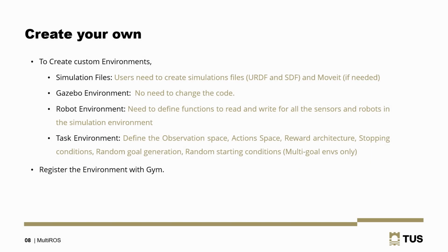To create your own environment, the initial stage is building the simulation of the task in the Gazebo simulator. So users can create a URDF file for their own robots or use the files provided by the robot manufacturers to spawn robots in the Gazebo simulator. Then using the URDF files, users can create or add objects and design the scenario of the environment. Here, users can specify the physics parameters and physics engine they require in the Gazebo world file. This Gazebo environment class is common for designing any task and can be directly used without making additional changes.